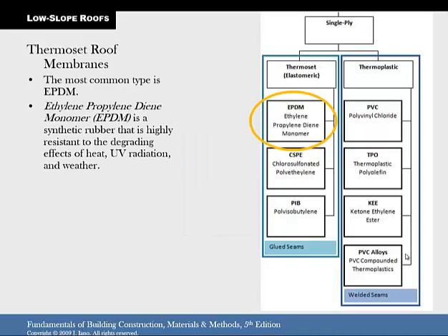EPDM is very popular. I've specified that before on jobs. And I think that's the one you can walk on. Like if you want to have a roof deck, if you have a flat garage or something, you want to have a deck on it, you could put an EPDM surface on there and walk on it.